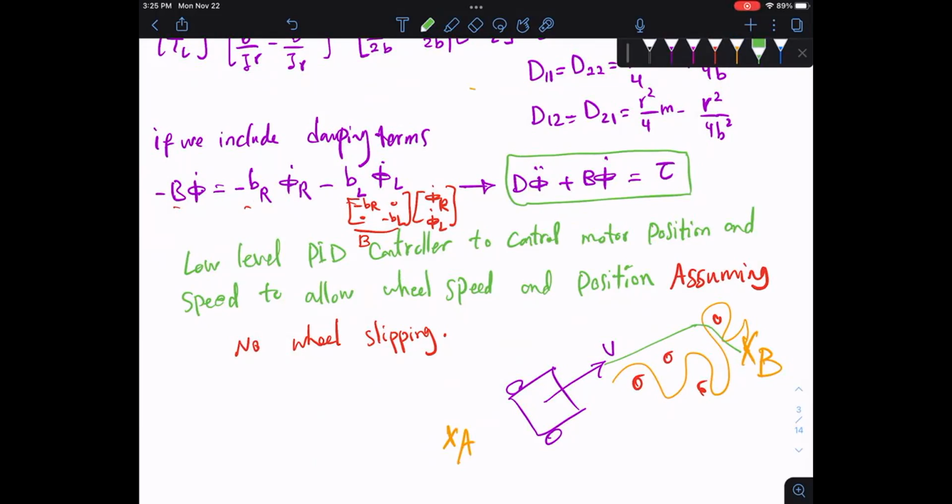That's what you have to control. Now to go on a straight line, we just said what should happen to the two wheels? Same velocity in the same direction. It will go on a straight line, hopefully, right? And then when you're turning, if you know the radius, you're going to adjust the wheel velocity and then go straight again, correct?